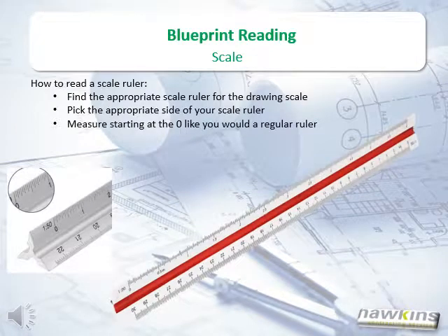How to read a scale ruler. Find the appropriate scale ruler for the drawing scale. Pick the appropriate side of your scale ruler. Start measuring at the 0, just like you would on a regular ruler.